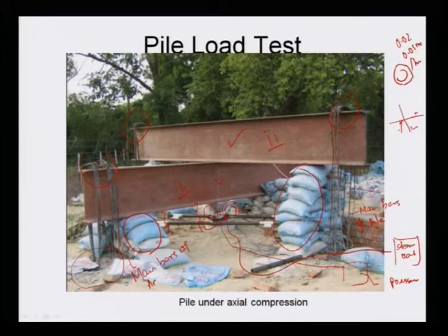Once the displacement reaches 0.02 or 0.01 mm per hour, you stop at that point, and that is your final displacement for your load intensity, say 10 kg per cm square. Then you apply your next load intensity. Like this you continue till the pile fails, or as per IS standard, up to whatever you get, so that you can plot load versus displacement.